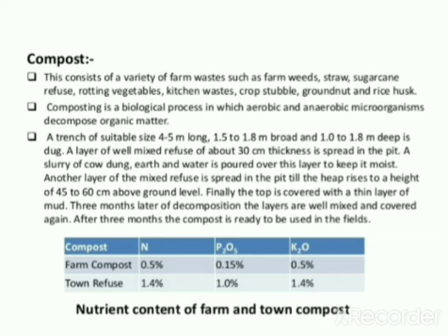A trench of suitable size, 4 to 5 meters long, 1.5 to 1.8 meters broad, and 1 to 1.8 meters deep is dug. A layer of well mixed refuse of about 30 centimeters thickness is spread in the pit. A slurry of cow dung, earth, and water is poured over this layer to keep it moist.